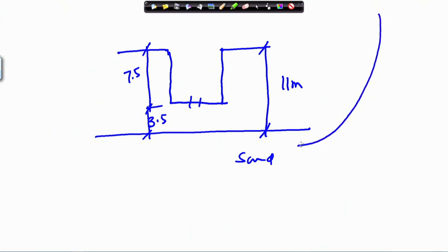Because of some source, water is there and it is giving some hydrostatic pressure here. If I insert a piezometer here, the water will rise up to that level. Since it is a clay layer, permeability is very low, you will not see the water, but when you punch this layer and make a piezometer, then we will see the water level.